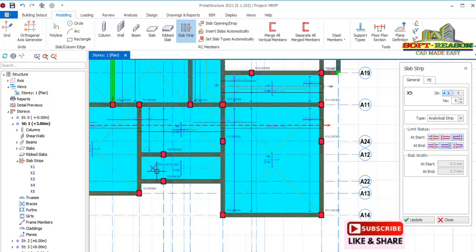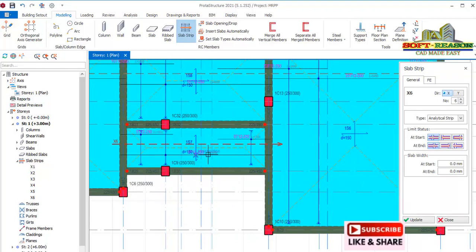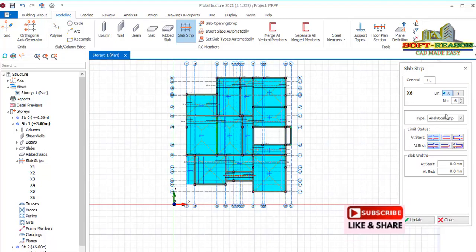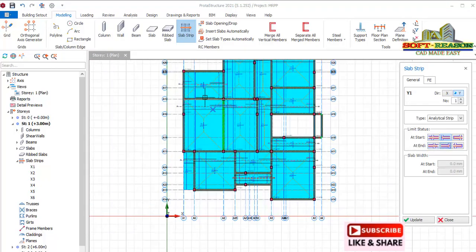So for this one, remaining in this direction, this particular panel is slab to slab. So pick this point, hold the control key to have a straight line. Have that inserted just like this. Okay. Go to the y direction, change the number to 1. Okay. And then we start at bulb and end at bulb as well.